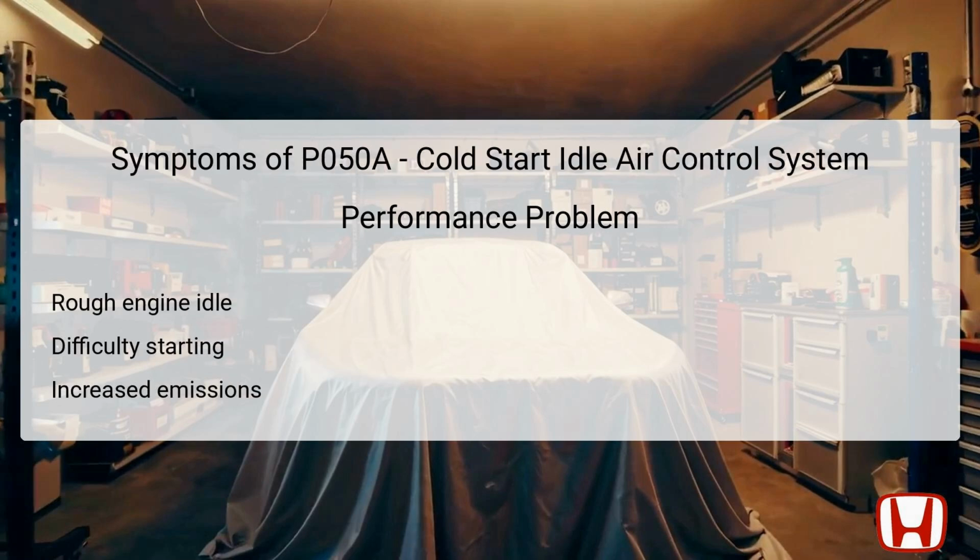DTC. Symptoms associated with DTC P050A may manifest as a rough engine idle, particularly noticeable when the engine is cold. Drivers may experience difficulty starting the vehicle, as the engine struggles to achieve the necessary idle speed due to incorrect air-fuel mixtures. Increased emissions can also indicate that the engine isn't operating efficiently, as improper air control can lead to a richer mixture and higher pollutant output.